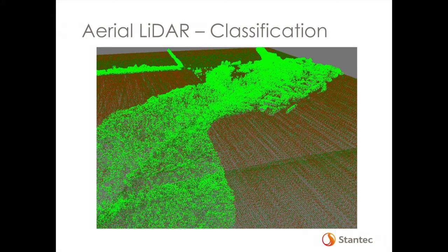Next, there are classification routines that can be run on this LiDAR data to layer or organize a point cloud. So you can run all kinds of automation on it. You take all the raw data, run it through a bunch of filters, and it will classify ground, low vegetation, medium vegetation, high vegetation, and what it detects as buildings. You can do power line extraction, and all these things are quite automated in some of the better software out there. A lot of the data we get is just classified into ground and non-ground, so we take it and reprocess it, and we can do more with it.